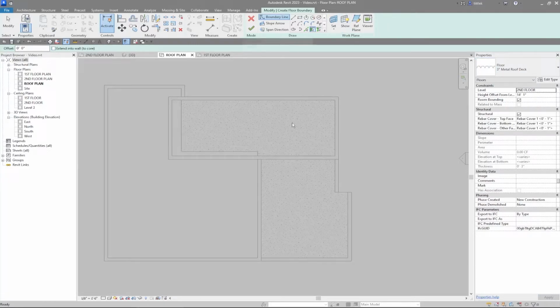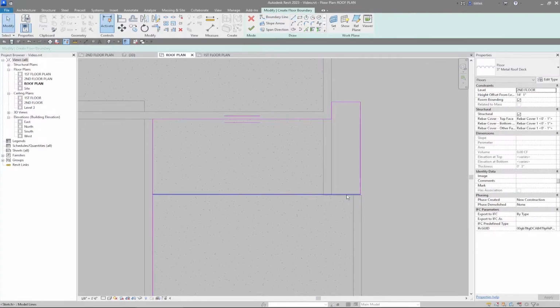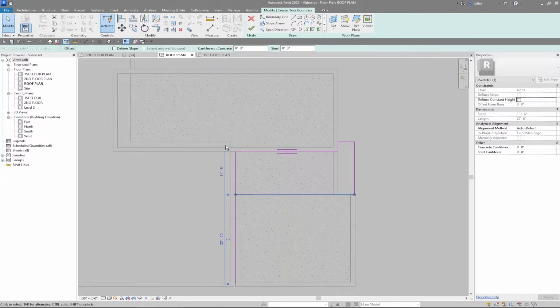We don't want to do that. And we can select these two walls. What do we say? We're going to do a line here. It's going to go out to the face of that, up here, over, and down. And we know that this line, we can use our temporary dimensions, drag that up to there.